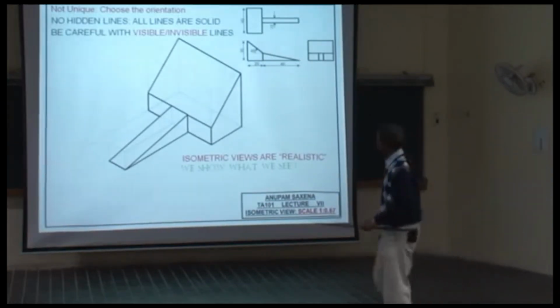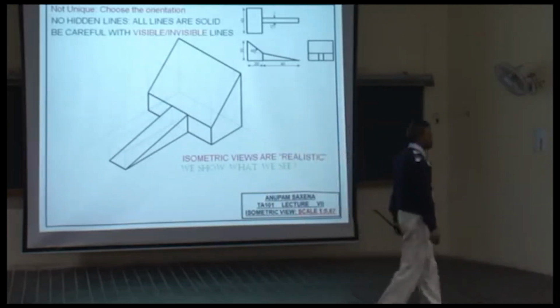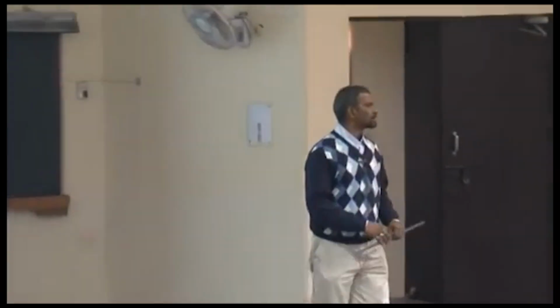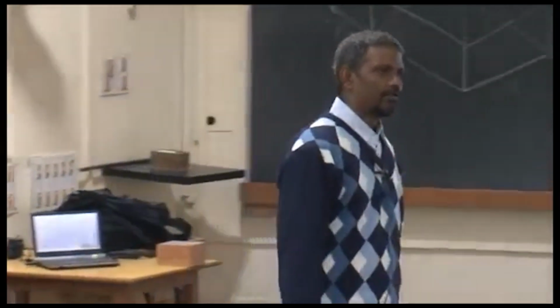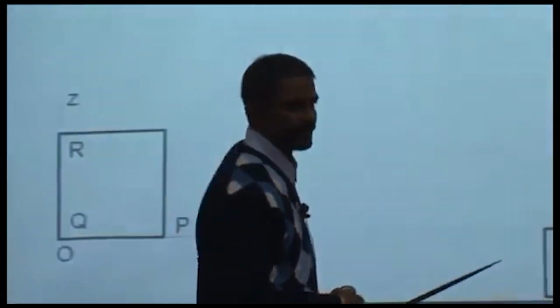Okay? So when we are drawing this isometric drawing, then we have to take the real values, not the foreshortened ones. Isometric drawing, foreshortened. Isometric view or isometric sketch, true values. All right. Something very important. Remember in the first class or the second class, and definitely in the first lab, you did a lot of exercises on ellipses. We are going to be drawing a lot of elliptical arcs or ellipses in isometric views.